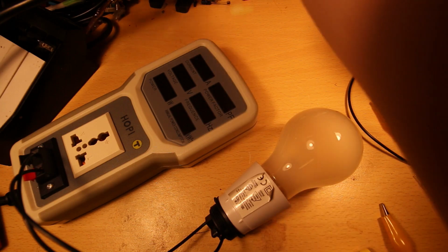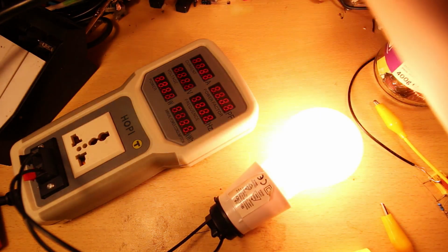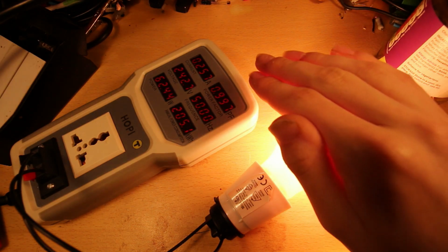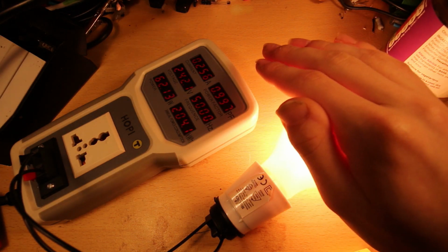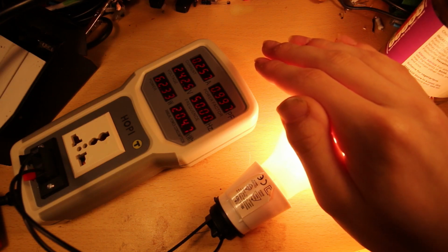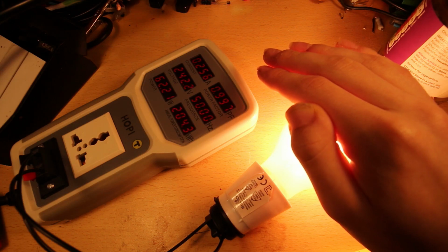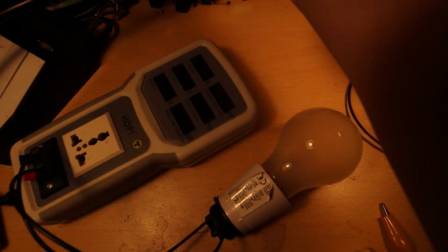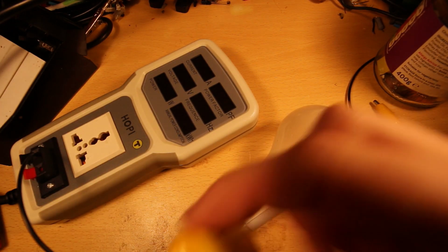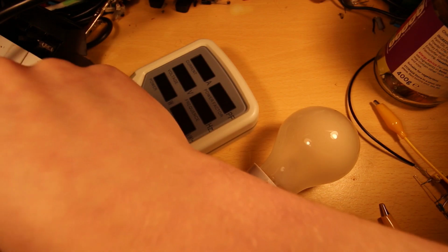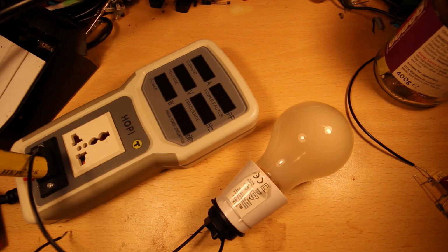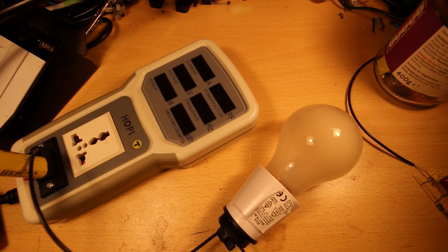But anyway, you will see when I turn the power on to this, the bulb turns on, so I'll shield you from that so you can read the screen. And we are drawing 62 watts, the power factor is 0.997, and it is drawing 250 milliamps. I will now turn this off, and we will put a big beefy capacitor in line with it. I will then attach these dodgy clips in order to put the capacitor in series with the bulb.